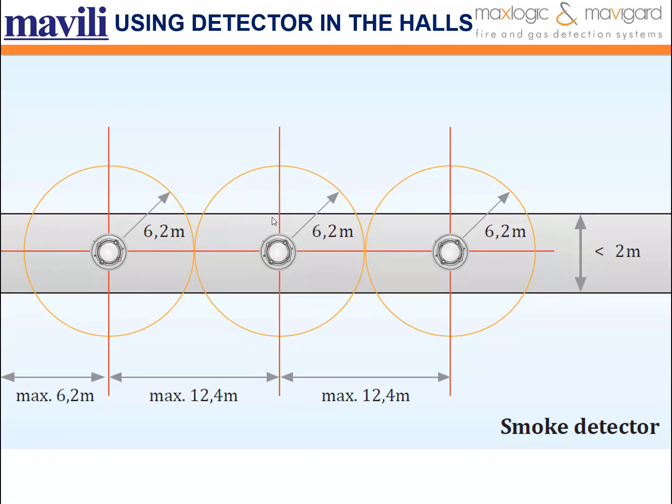Like the heat detectors, if the protected area has a sloping ceiling, for detectors at the top or near, the horizontal distances given above can be increased by 1% for each slope degree, up to 25%.